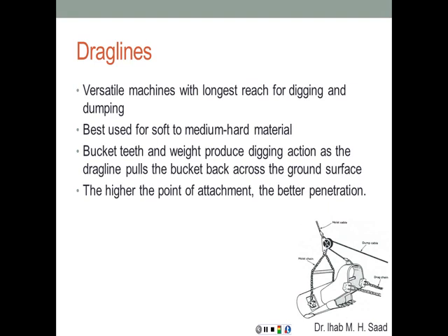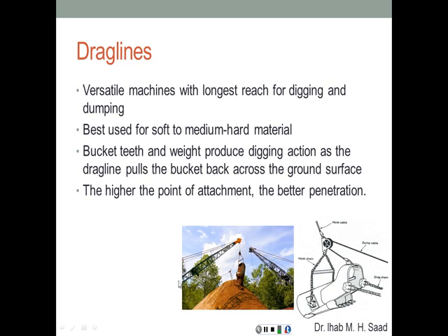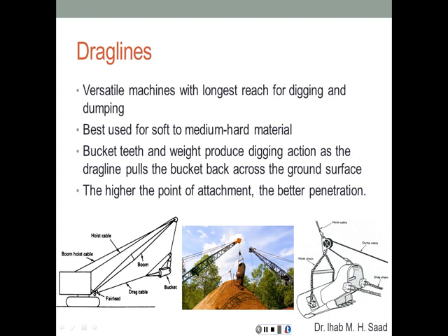And here's an example. This is basically the bucket of that dragline. And here it shows the long arm. You reach, you drop it, and then you drag it to fill it with soil. And that's another view. So of course, the longer the boom, the higher the point of dropping that bucket, the more efficient you're going to be in filling that bucket. You drag that cable to bring it back, and then you're going to turn and dump it in a truck or a pile of soil.